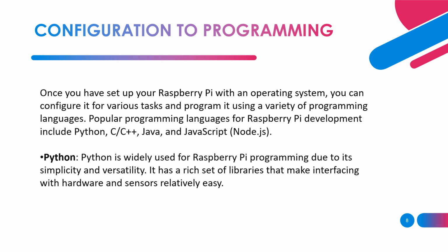Configuration to programming. For configuring Raspberry Pi in Raspbian, we are using Raspbian with PiXel desktop. It is one of the best ways to get Raspbian started with Raspberry Pi. Once we finish booting, we will be in the Pixel desktop environment. Now to open the menu, you need to click the button that has the Raspberry Pi logo on it. This button will be in the top left. After clicking the button, choose Raspberry Pi Configuration from the preferences.